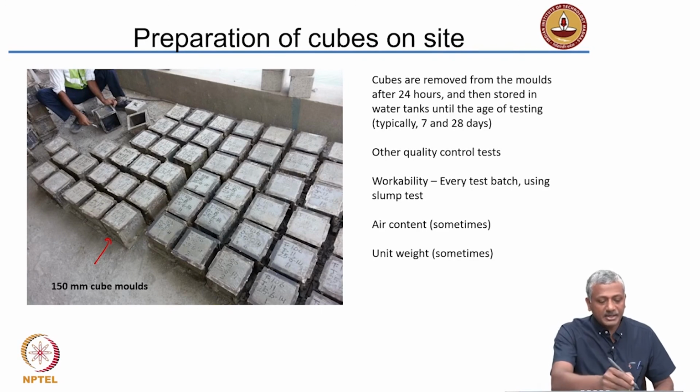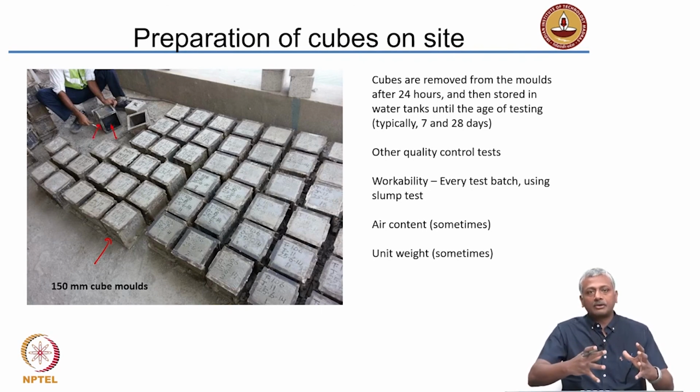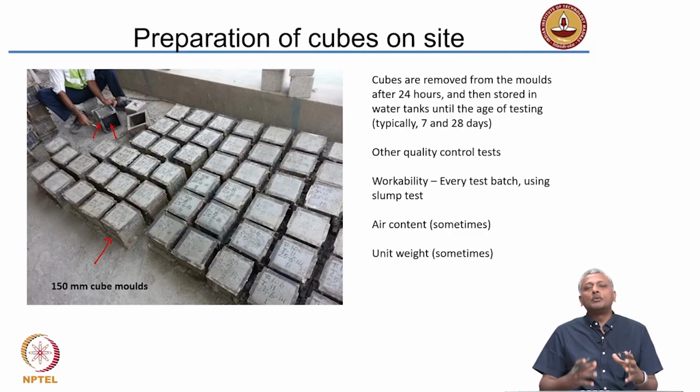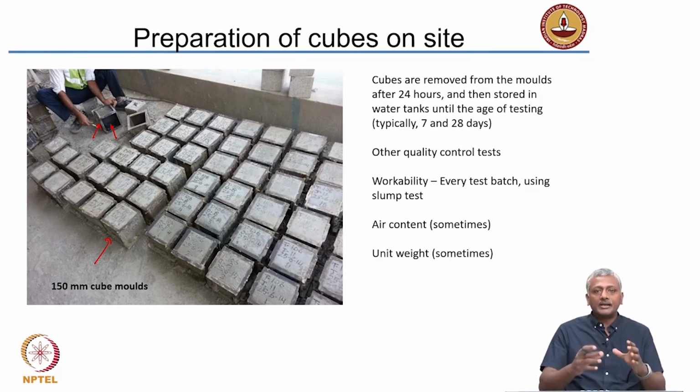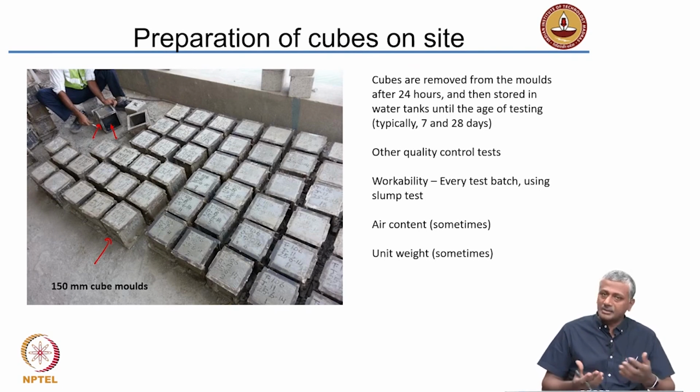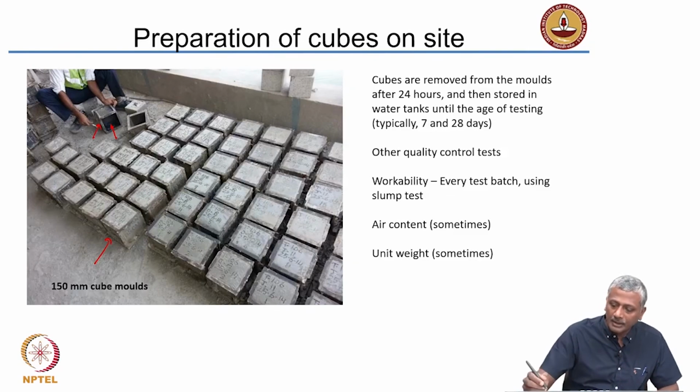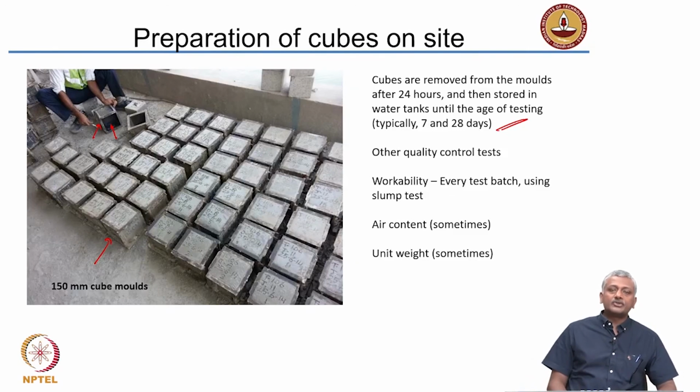You can see this person is actually removing the molds, okay, to extract the concrete cube from inside. Typically the removal of the concrete from the mold is done at 1 day. That means the day after the concrete has been placed, it is removed from the molds, and then it is cured underwater in most cases. In most construction sites, the curing is done underwater, okay, and they are cured until the age of testing, usually 7 days or 28 days.